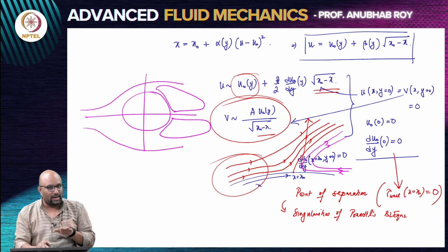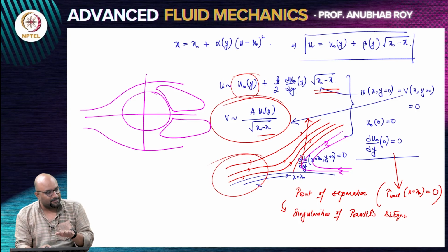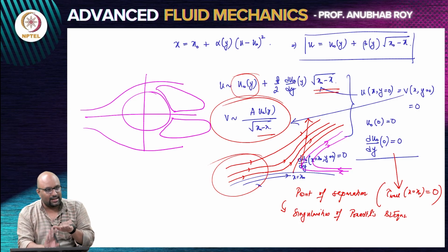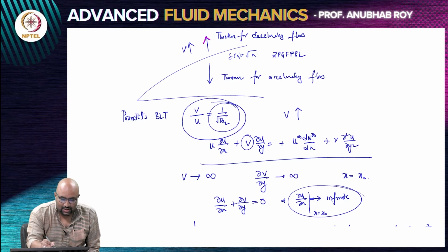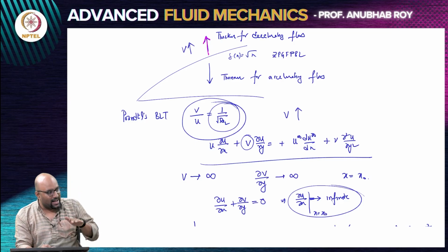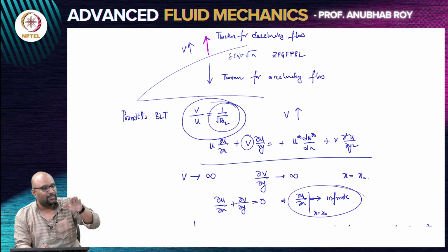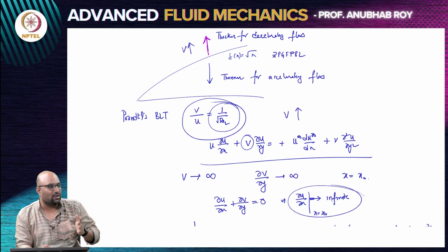You think of the streamlines moving close to the surface, but there is constantly increasing vertical deflection. With this, what we are saying is that the vertical velocities are increasing. So, as a streamline or as a fluid parcel is moving close to the surface, the amount of vertical velocity it experiences continuously keeps increasing in a decelerating flow, and after a point it is just not able to stay close to the surface and it departs off entirely, it takes off.